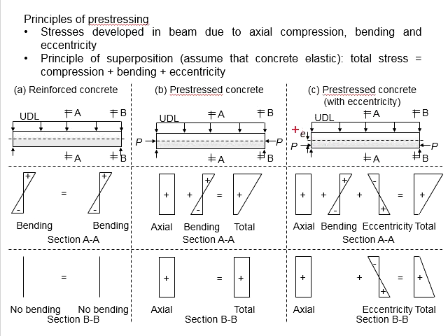Also, you will need to observe if there is eccentricity. In some conditions, there may be eccentricity at the midspan but no eccentricity at the support. In that case, for the midspan, you will have to consider the effect of eccentricity. Then, for the support without eccentricity, the effects of the eccentricity cannot be considered.